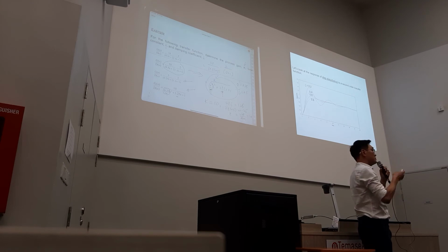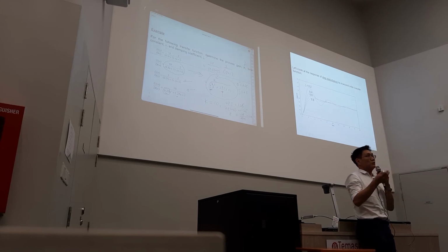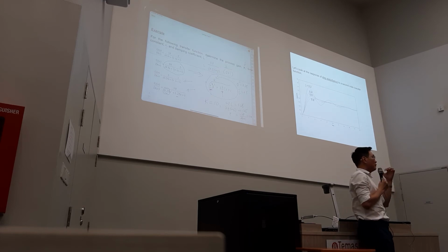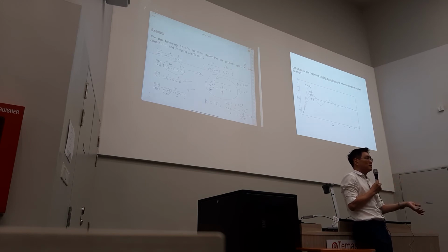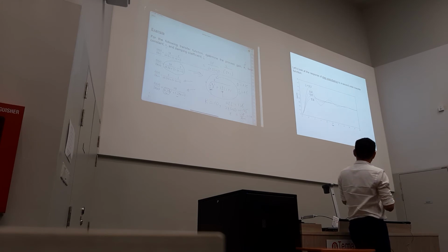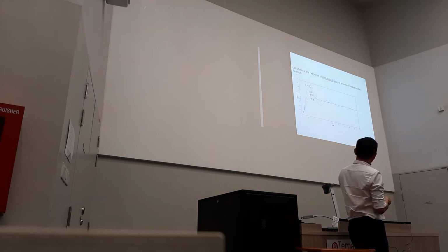Which means that if I change the system, at first the system will shoot very high. Then after that it stabilizes. The smaller the value, the more overshoot will take place. So among all this, we must choose a certain value. If I have a process design and from my second order mathematical model I managed to find my damping coefficient, and it's too small, then I will need to change my system again to make the damping coefficient fall in a certain range. What is the range that we need?